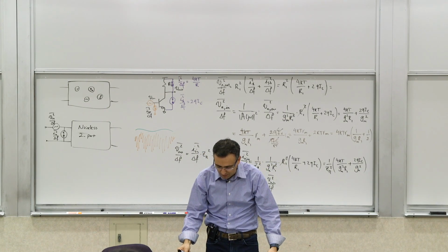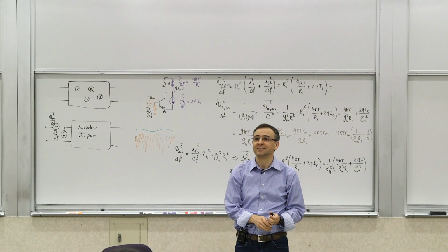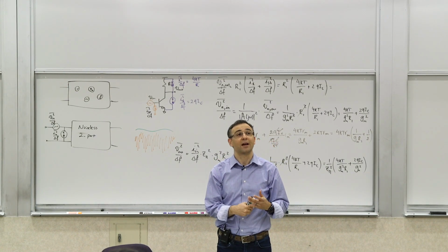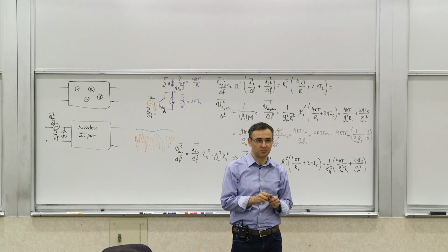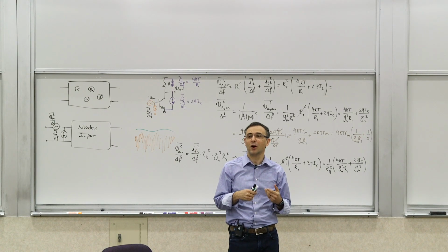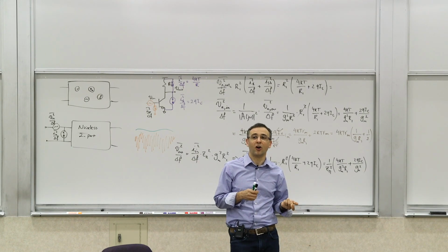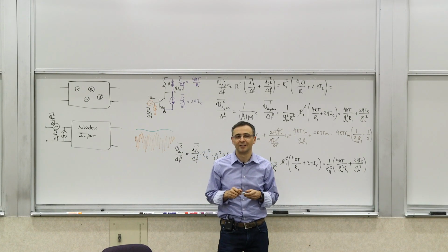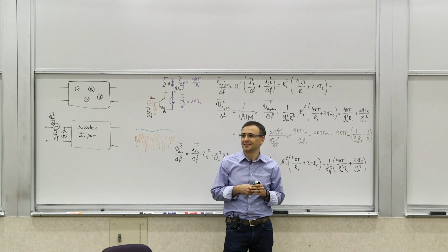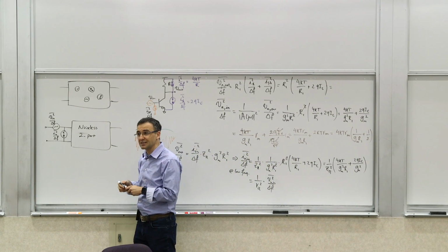Why do you think it's a tricky proposition? Yes? You might add your own noise. That's one reason it may be a tricky proposition. Yes, that's right. But why are we particularly prone to that, as opposed to measuring the gain of an amplifier, which is not as hard? Yes? Because it will have really high frequency components, so if you have even a little bit of capacitance on your probe, if you want to, for example, measure the frequency spectral density of this thing, you're right.